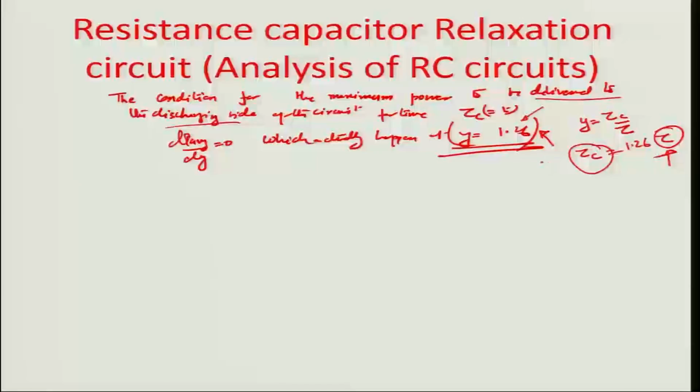Now let us look at what this Tc corresponds to. So obviously it is the amount of total time that is needed for the maximum power to be delivered, which would definitely include the charging time. So if I look at different components of Tc, it would be the time of charging plus a small amount of time which is spent for the spark to happen, the time of spark, T spark, added on to the charging time.